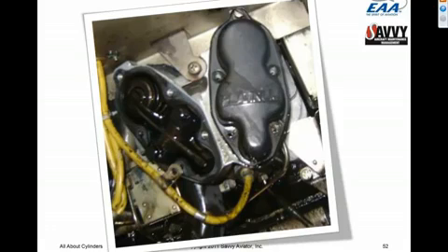Why did this happen? The airplane had just come out of an annual inspection. The shop changed the number 2 cylinder, and obviously the mechanic got distracted and didn't properly torque down the rocker covers. The left rocker cover, which is on the exhaust side, departed the premises and was never recovered. The one on the right side, if you look closely, you'll notice that 4 out of the 5 retaining screws are missing, and that rocker cover is just dangling by the top screw.